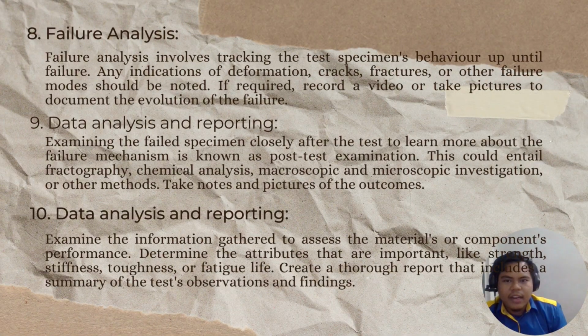Failure analysis. Failure analysis involves tracking the test specimen's behavior up until failure. Any indication of deformation, cracks, fracture, or other failure modes should be noted if required. Record a video or take a picture to document the evolution of the failure.